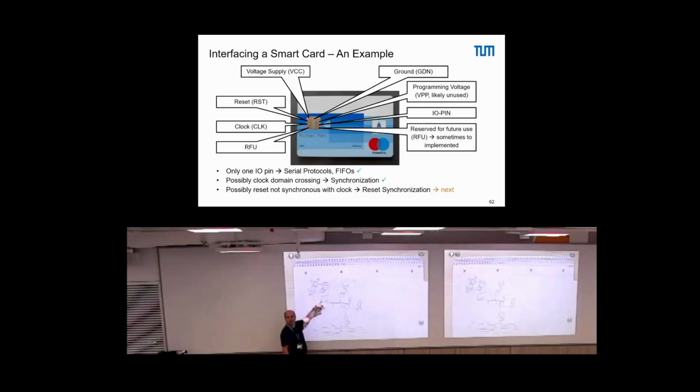Not really, right? So only making the flip-flops here synchronous is not enough, because we can still, relative to the clock, come to a point in time with our asynchronous reset from extern that causes problems for our timing for the flip-flops. So what actually helps is if we synchronize here and here, because then we can do a good timing calculation, right?